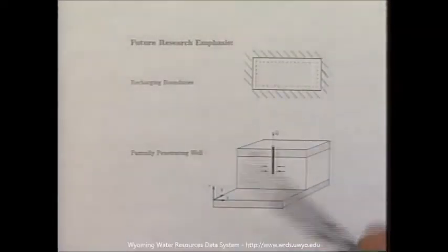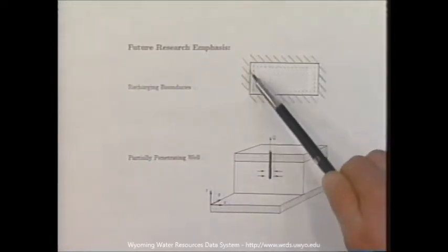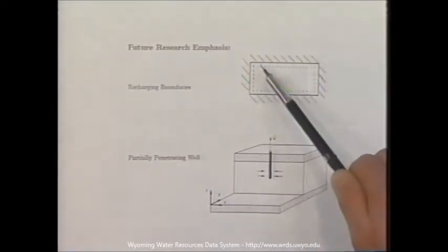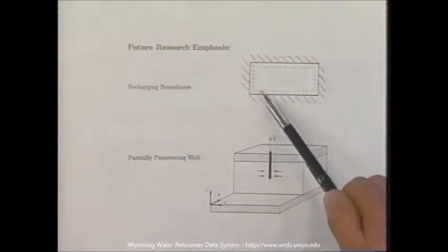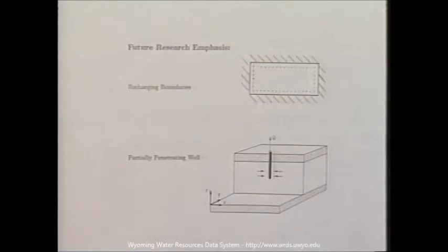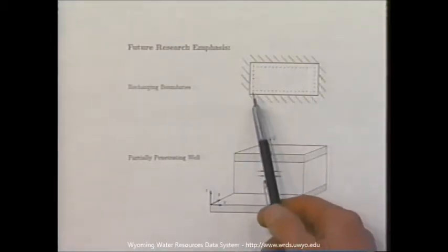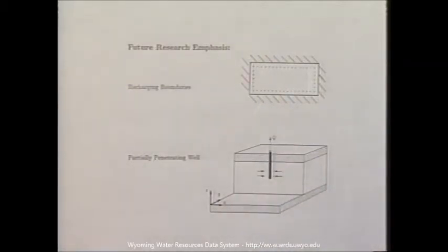So one of the ideas to handle that difficulty, to get it back to a nice finite domain, is to solve the larger problems, calculate what type of recharge you'd need to supply the fluid into your finite domain, and then, in essence, work the problem with a no-flow boundary condition, whereby you will recharge the boundary to maintain the flow going into the system.